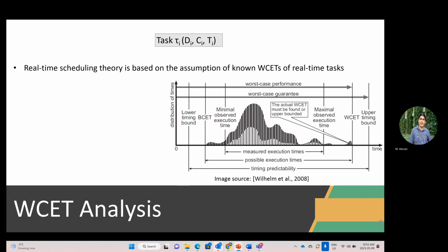Why? This is being discussed in electronics, but in fact, operating at a certain voltage is not guaranteed for electronics, because it depends on what temperature you're operating at. If you open any of the data sheets we have, including the SMU6X, you will find what we call operational conditions. It tells you, I give you this error within this temperature variability, and I give you this error with this temperature variability. Usually it's tested in labs before the product is released. So this variability is a factor. Excellent, especially for embedded systems. What else?